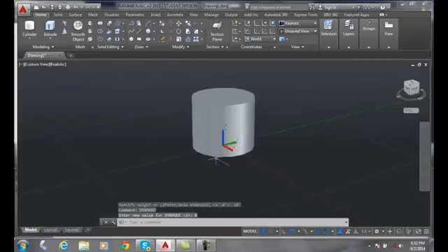And now we're going to just draw a line. And we're saying, from where do we want it to go? Well, we're going to go with the @ symbol first. And we're going to say we want 6 foot. And then we want to go with the less than symbol, and then 30 for the angle. And we're going to do a comma, and then we're going to say 2'6". I'll put the inch mark, we don't have to.